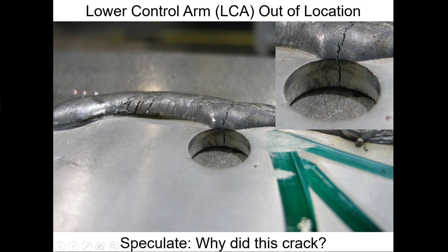If you flipped around to the other side of this and inspected it, you would have noticed that it's cracked. The control arm is cracked right through that base metal. Now, I did the repair to kind of show the technique, but this cradle would be scrap if you see that. Just to give you an understanding of why it happened.